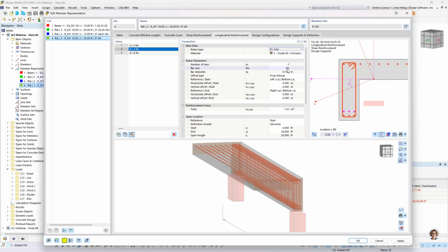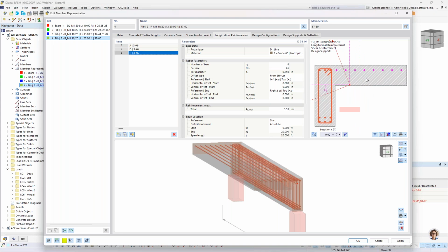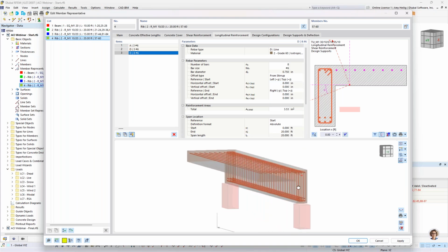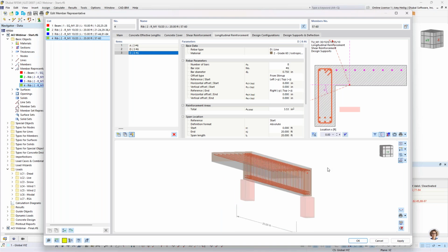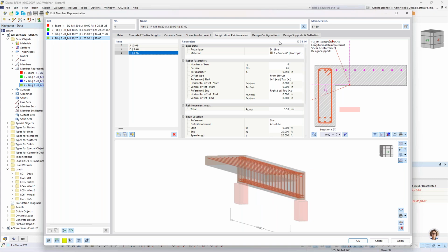This line option allows me to place a line of reinforcement, and I can specify the different offset, either left or right or top or bottom, with this input option. And finally, we have 8 number 6s that are defined in the surface effective width itself. This was also defined with the line option. I modified the offset here, such as 8 inches, so that we can input this longitudinal reinforcement within the slab element. This is pretty simplified for today because we'd probably want to create different zones with different longitudinal reinforcement, but this is just a little bit of an overview for this simple example.